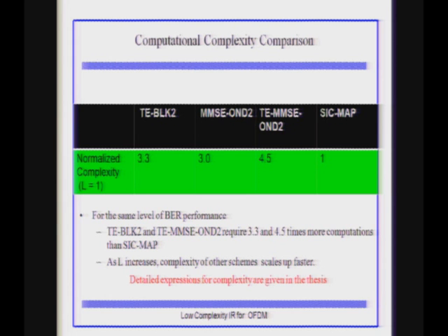If we talk about just the plain non-iterative scheme, the standard MMSE equalization, even that is 3 times as complex as this. This is per iteration, right? Yes, this is per iteration. Do they scale linearly with iterations? As long as L is constant, everything is linear. If you do 3 iterations, it will be 3 times this.